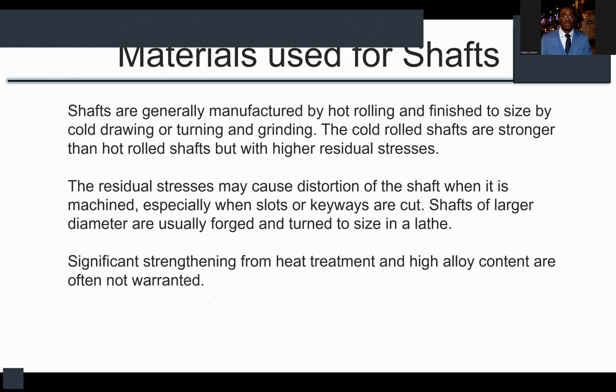All right. So what we usually do is we heat the metal up until it's close to its melting temperature, and then we begin to draw or we roll. We have very large wheels that the metal is drawn through, and as they are rolling, they press it to the correct dimension. For hot rolled metals, as the metal is cooling down gradually, your stresses are relieved also. So hot rolled metals have lesser residual stresses than cold worked ones.